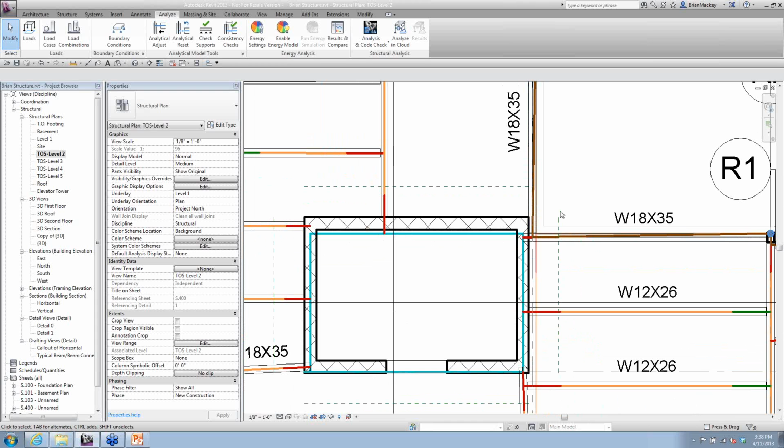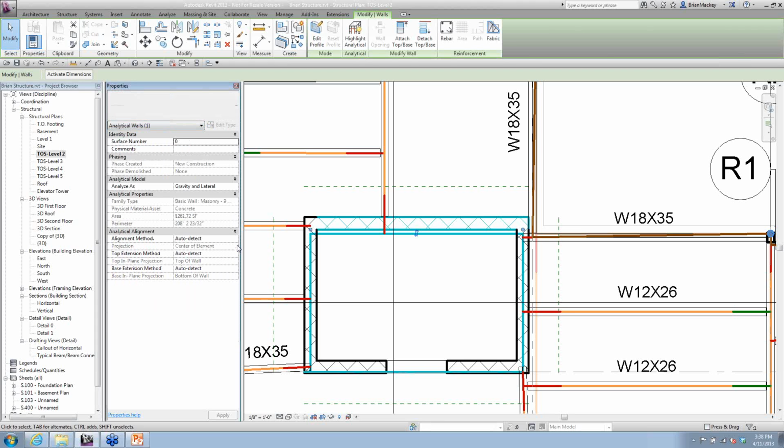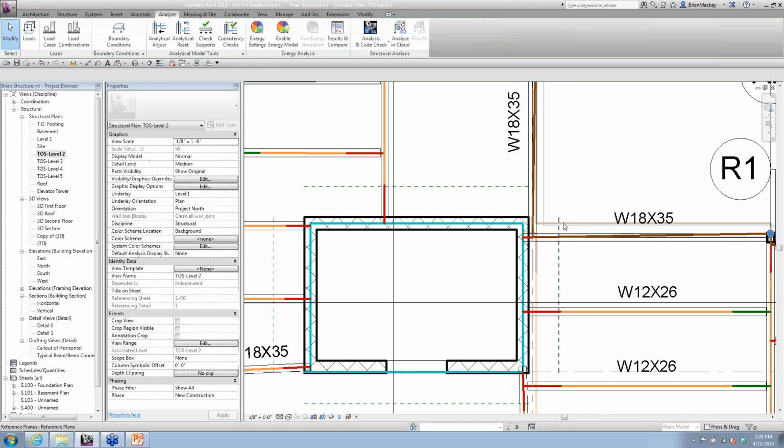So as you start going through and adjusting it, really going into saying, hey, I want this analytical line there, that analytical line here, it can be a whole domino effect of objects, and they can start changing around to be what you're maybe not intending for the analytical side. So again, I moved that one. Now this wall down here has it outside of the wall. So I'll tab to get to that wall. Maybe I might not be seeing the wall here, so I'll just go back to my 3D and do that one in the 3D.